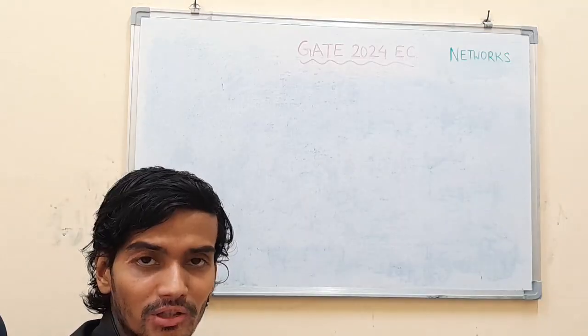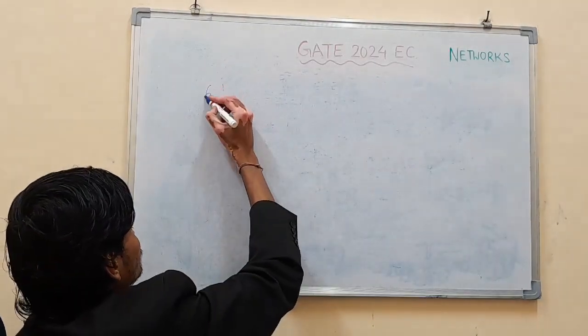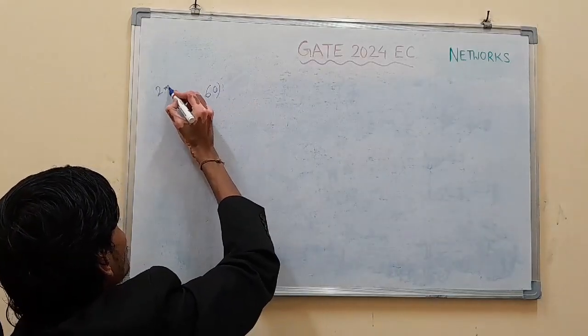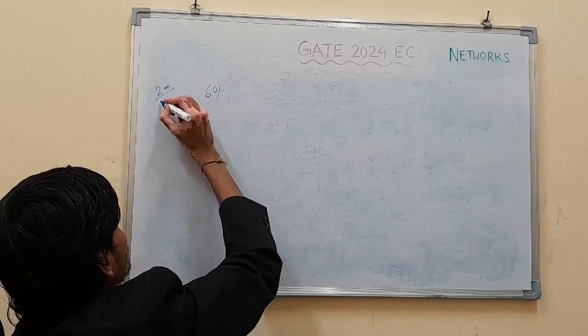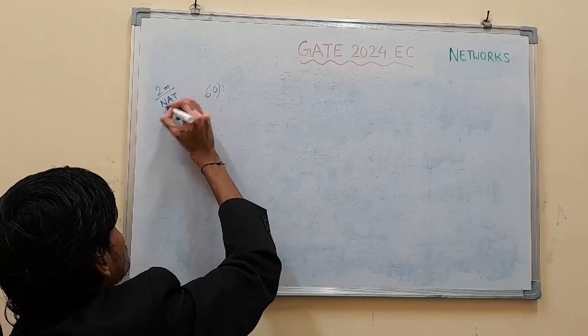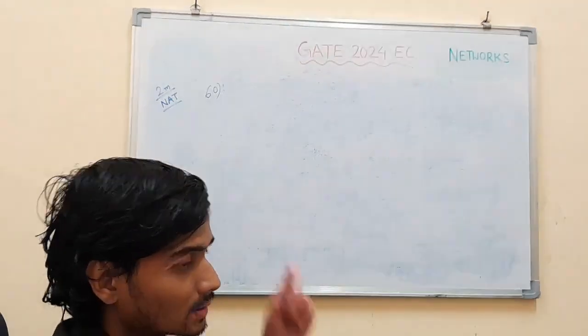Maximum power transfer to load RL requires RL equal to RTH, by the maximum power transfer theorem in DC networks.